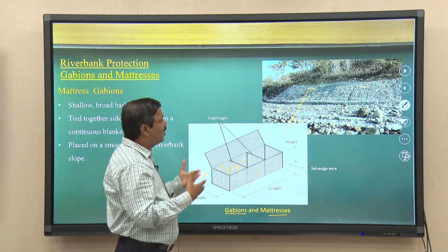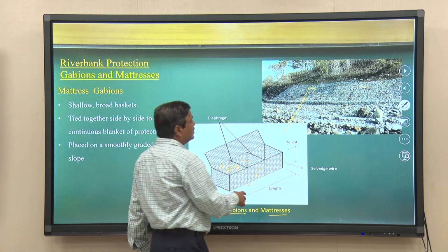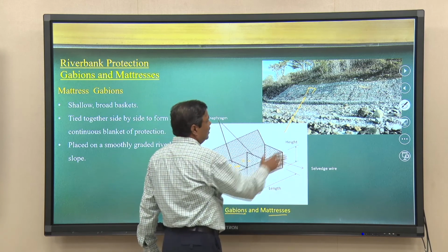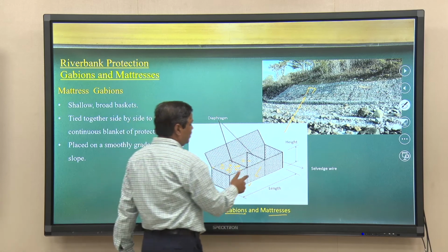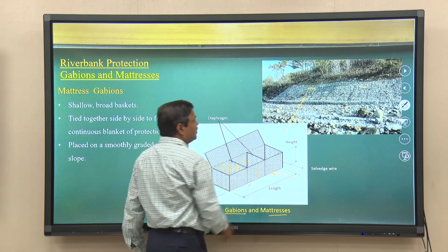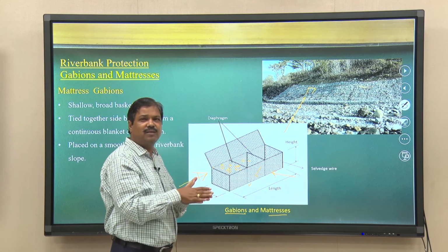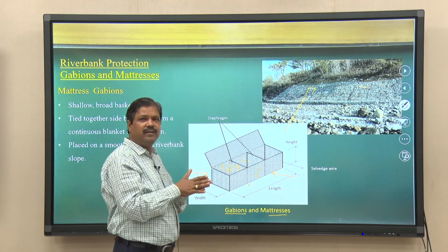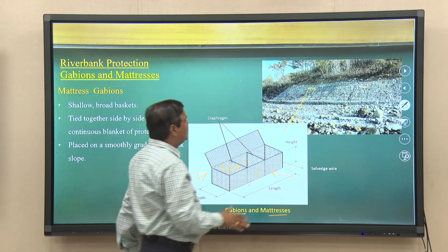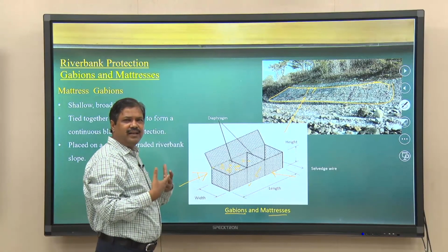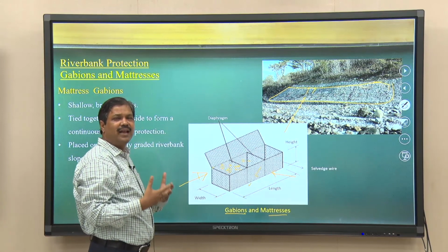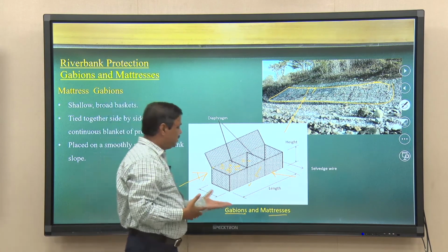So, that is the reason nowadays we use this concept of Gabion matrix on river bank protection, where we need to protect it, because it is cost effective in terms of reduction of the thickness of the stone revetment, and as well as it creates a monolithic structure. Okay, a single structure, so that any sort of failure mechanism can be prevented because of the Gabion matrix.